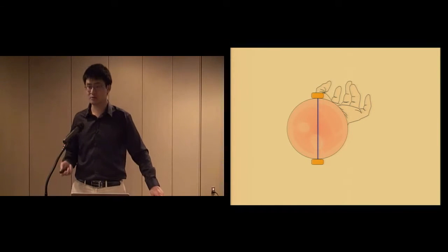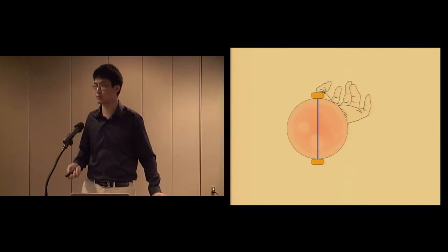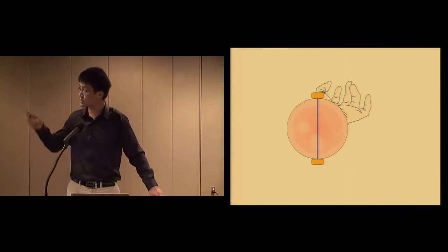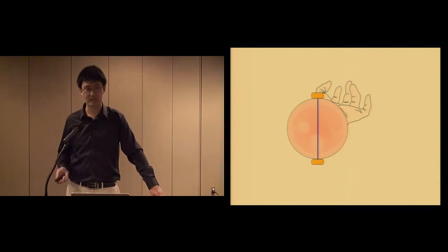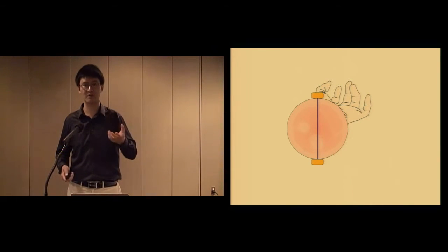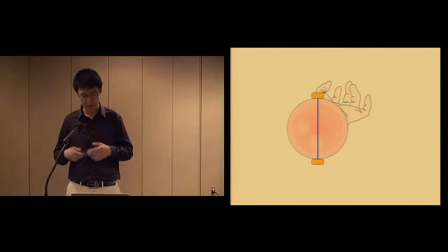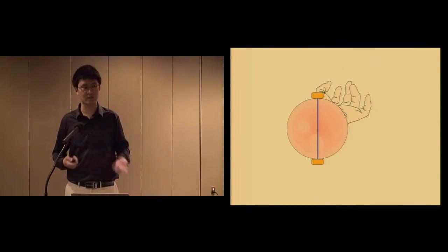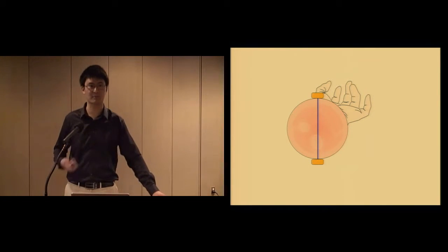We create a 300 microamp constant current AC signal running at 40 kilohertz between those electrodes. The voltage of that signal is going to depend on the impedance distribution along the electrical path between those 2 electrodes. And so if we measure the voltage difference between those 2 electrodes, we can then infer the impedance along that electrical path, and we use the root mean square measurement in our system to smooth out those voltage fluctuations and actually perform that calculation.